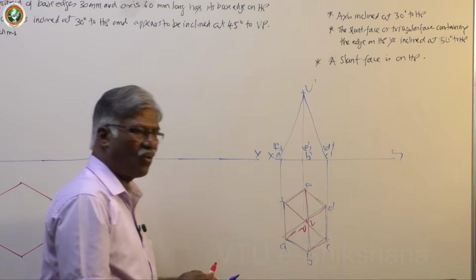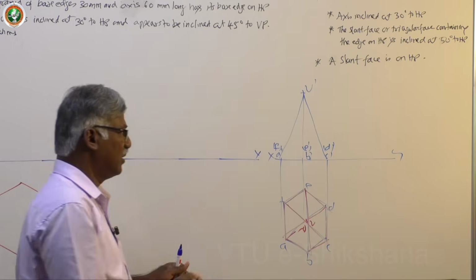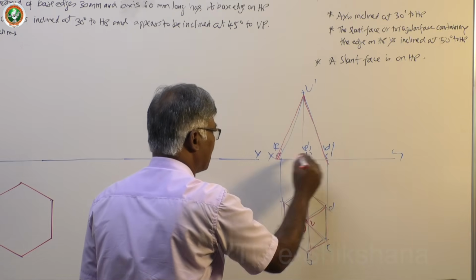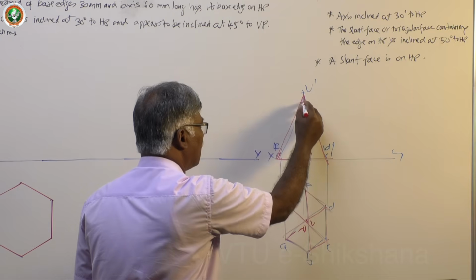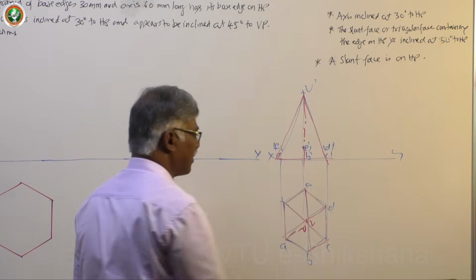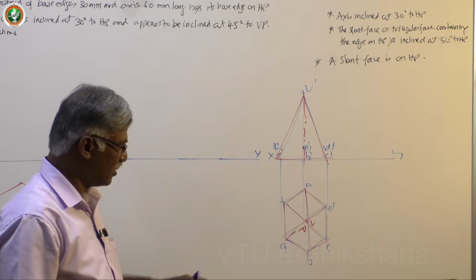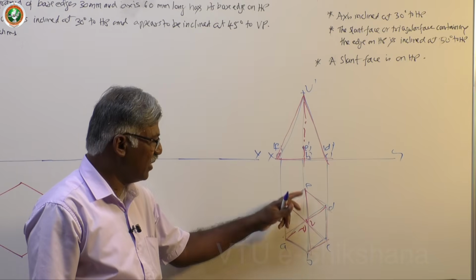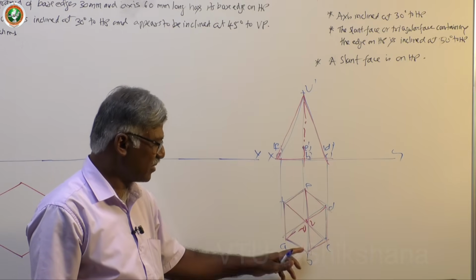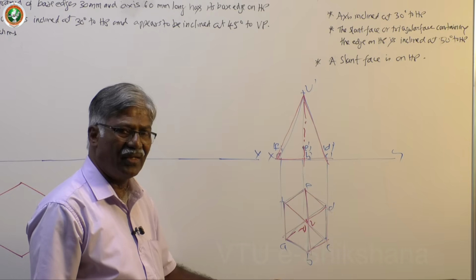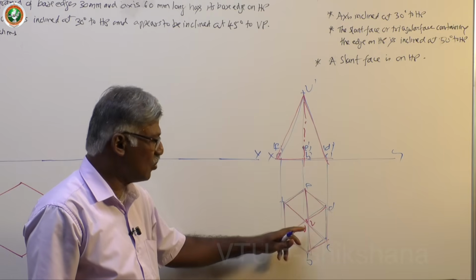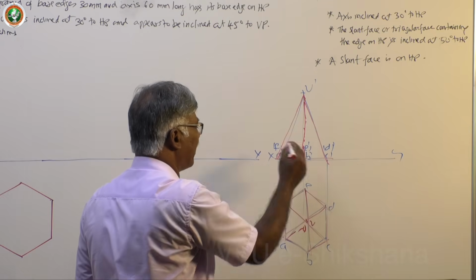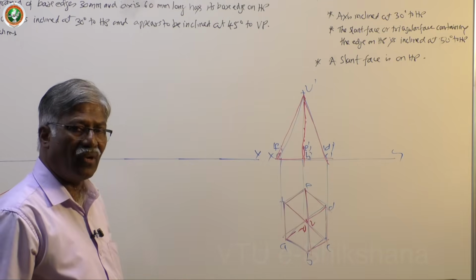Now what all is to be drawn dark? See, normally we complete this. So now this is identified as the axis. This is wrong, because VB is visible and VE is just the backside of VB, that's why it coincides with that. There is no scope for the axis here, so you must draw a dark line. This is very important information for you.